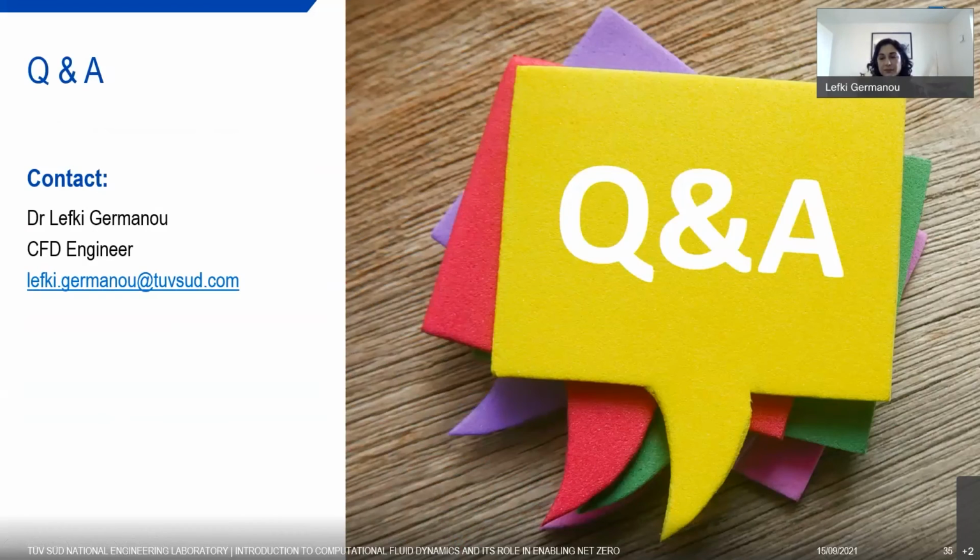Okay, I've got two questions here left. Bear with me on this one because the two of them are linked. One of them is: was wind direction over the building considered, i.e., would the recirculation zone push the plume down or back towards the building? And the other one, which is linked to that, is: on the hydrogen dispersion study, was any consideration made for a no crosswind condition? Wouldn't this be the worst case scenario, as there would be no wind to disperse the hydrogen, and so it would build up around the vent, potentially within the pedestrian zone?